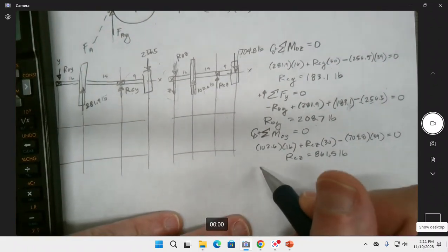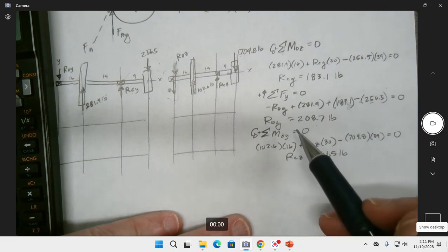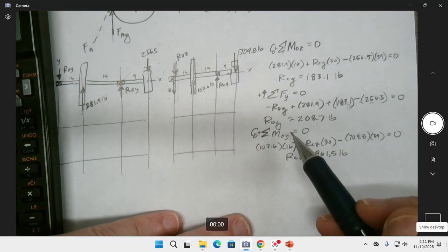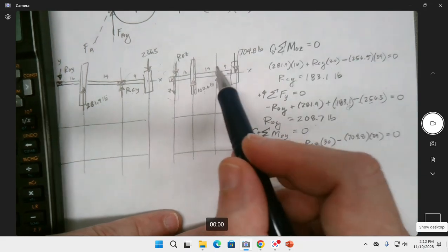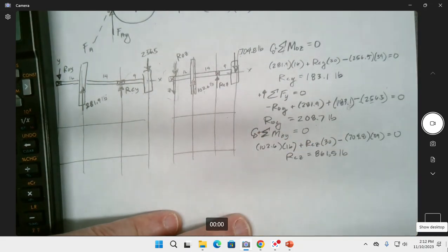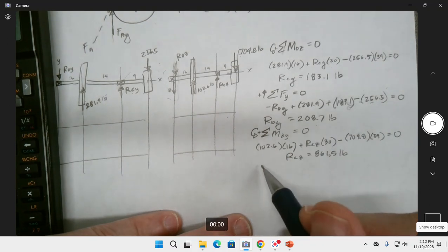I think so. Maybe. I don't think our stress concentration, actually I think this was a terrible problem, I just realized, for our stress concentration, because in order for it to matter, that needs to happen at a gear. There's no keyway at the bearing. But I can just see, because of this, I think our maximum moment is going to be right there. So it's going to ruin our plans. Ruined it.